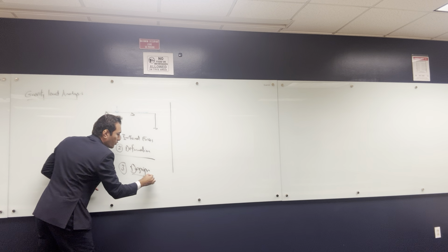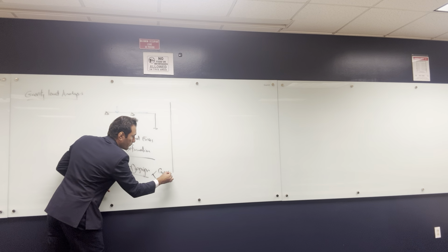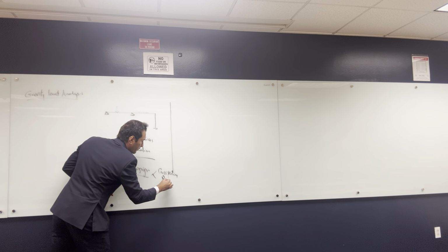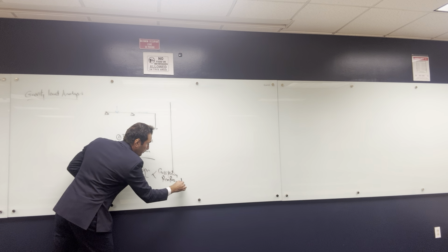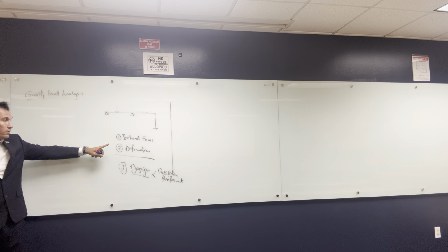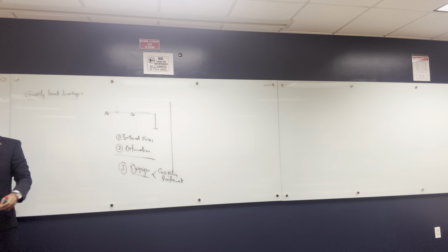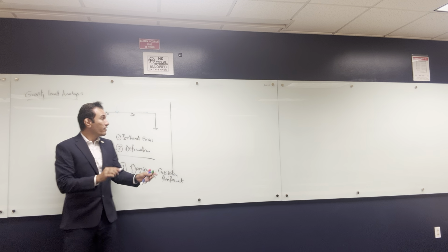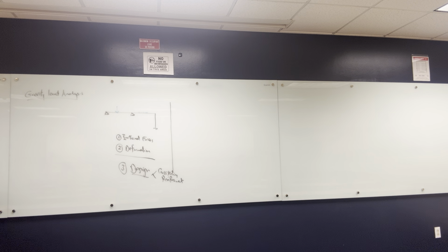What does design mean? Getting cross sections and reinforcement. So that's what we do exactly as structural engineers. First we build the system, get internal forces and deformations, and then design: what cross section I should use, either wood, concrete, steel, whatever. You need to describe to me how this cross section looks, how much steel is in it, okay? That's what we do as structural engineers. Same thing if it's lateral load. So that's number one. Number two, lateral load.